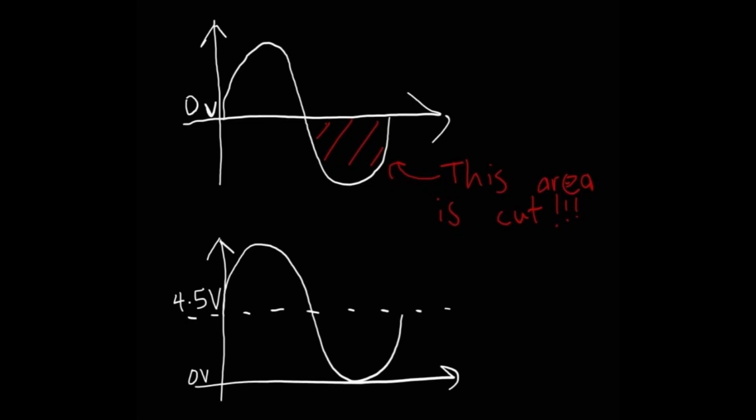This is necessary because the op amp operates on a single 9 volt supply and cannot process negative voltages. Without this biasing, the negative half of the waveform would be deep clipped. Centering the signal at 4.5 volt allows for symmetrical amplification, preserving the full shape of the heartbeat waveform.